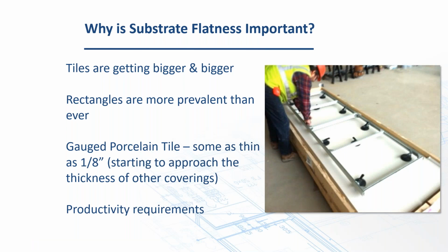Why is it so important? Well, tiles are getting bigger and bigger and bigger. Here we show what looks like a 1 meter by 3 meter gauged porcelain tile. They're much larger than that even today. Some are 5'6" by 10'6", even larger. Tiles today are no longer just square. Rectangles, planks, things like that are very, very common. Some gauged porcelain tiles are as thin as 1/8 of an inch, and so they can actually curve or conform, if you might, to irregularities. So it's important that everything be flattened out properly.